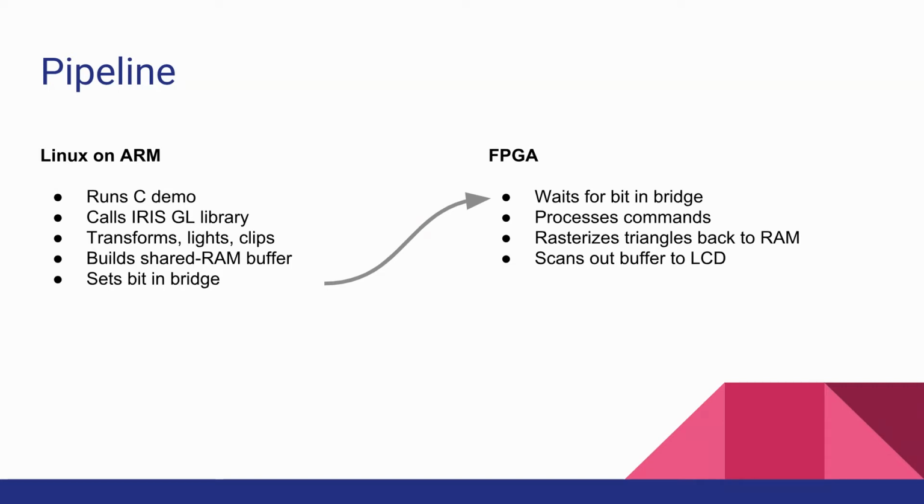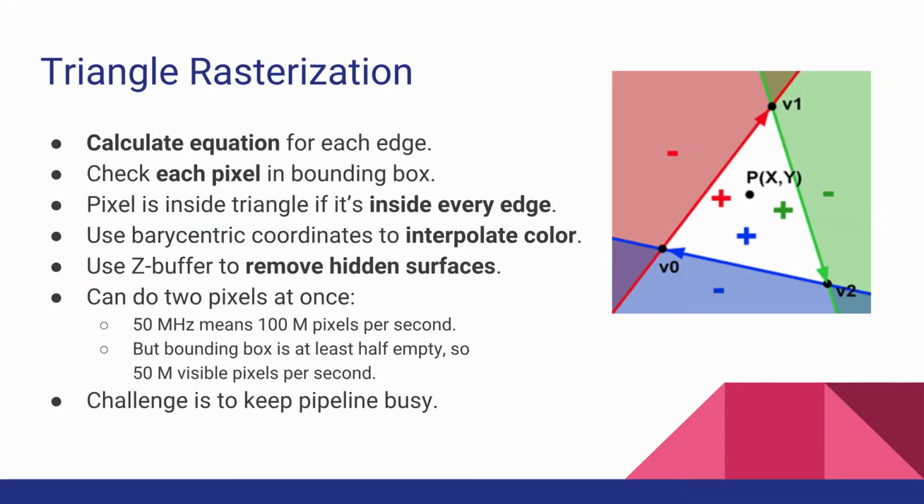Yeah, so we got this great LCD. It's a touch panel LCD, and you just hook it up like that to your FPGA. I'll open it up later, and we can see all that. So it's constantly scanning out to the LCD. The LCD doesn't have any memory. It's not like some of these where you can draw stuff and let go and it keeps it. It's more like an old style CRT, and you have to update it all the time. Okay, so that's the basic breakdown.